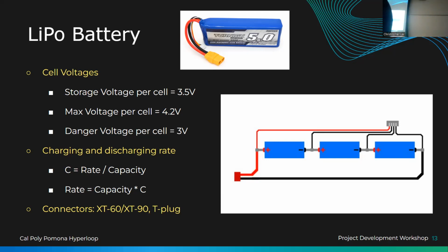This one's a 6S LiPo battery, which means it has 6 cells connected in series to each other. The discharge rate for this one is going to be 130C, which means that this tiny little guy can pump out about 130 amps into a robot, if the robot needs it. This one's my most powerful battery. I love it. But it's out of stock now, so I'm sad.